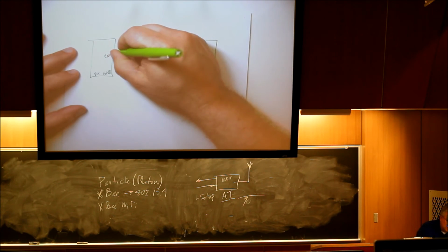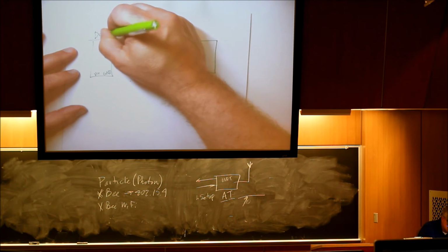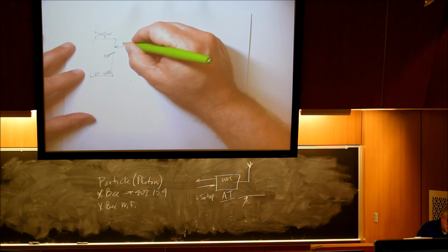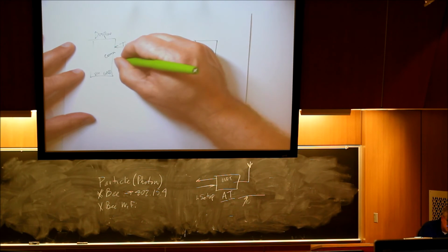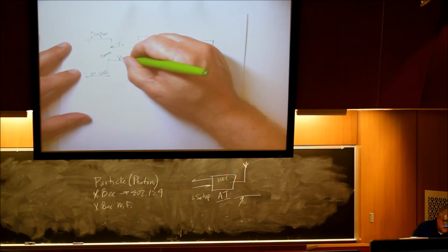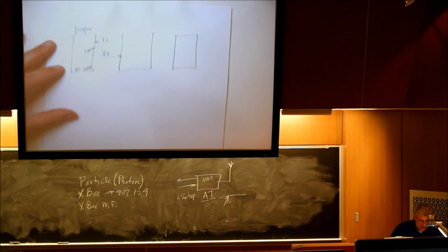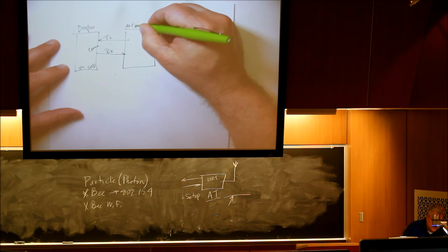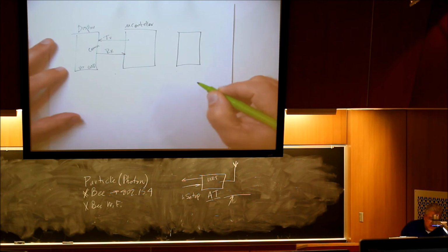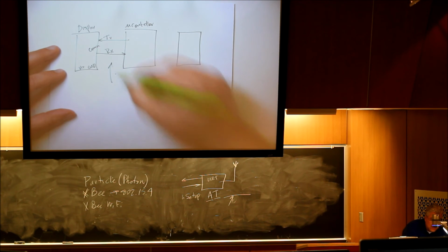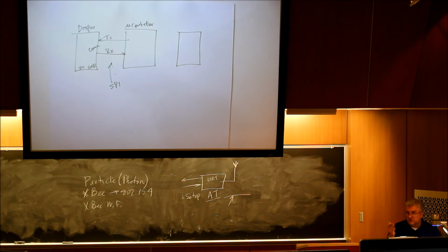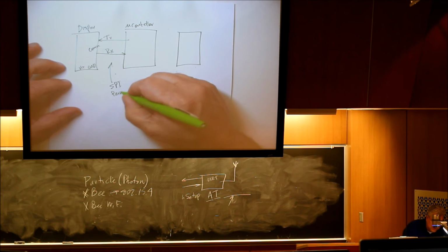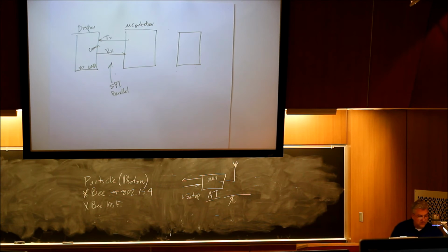So it might be that your display is going to rely on UART, and so you obviously need from our microcontroller a transmit and a receive. It may instead be the SPI bus. You need to identify which it will be. And if you chose one that has parallel, of course you have to worry about the parallel lines.